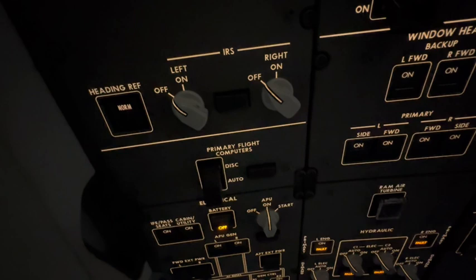I'm not going to go too deep on this one. It's basically to align the aircraft. Airplane knows where it is. Airplane knows where it's going. Now, the button on the left of the IRS knobs is the more interesting one. Heading reference. Why is it interesting? Because the switch is a manual way to change between magnetic north and true north. When the heading reference switch is in a normal position, the AFF auto flight function uses magnetic north for its heading reference. When you press that button, it goes into true position. It uses the true north for heading reference.